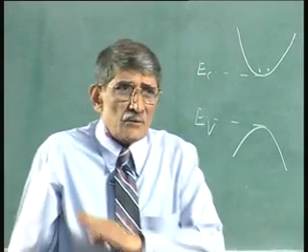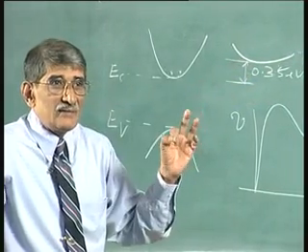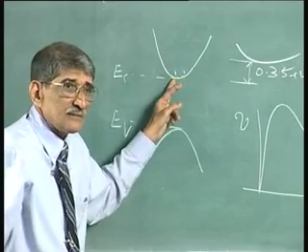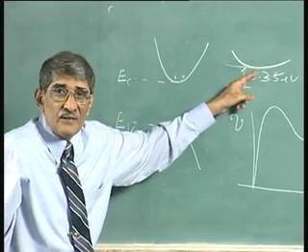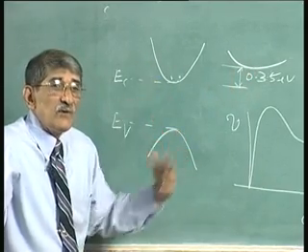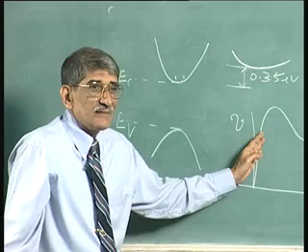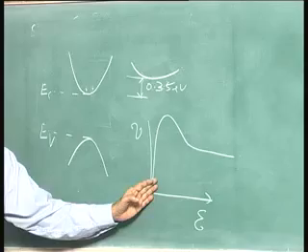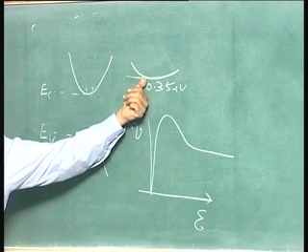So, the electron has no chance to go into that valley. Now, you can see the beauty of the whole thing. You have electrons residing here which cannot acquire energy to go up to that point, and you have electrons which experience very high field. So, that means you are on this line.